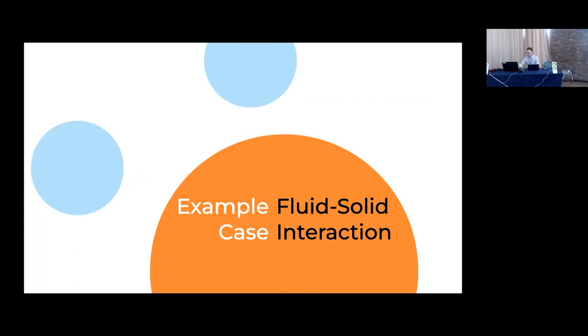So the question is: is the point D displacement field solved for the displacements of the points directly, just like in dynamic mesh, or is it solved for the cell centers and then interpolated? For this particular solid model, it actually solves at the points. There's no interpolation. But there are ones that solve the cell centers and then interpolate to get a point D field. In this case, this vertex-centered one really is solved at the points.